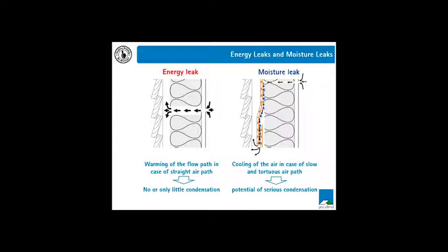If we start to build semi-airtight structures, then we create more tortuous, more convoluted pathways through the construction systems. This gives the moisture-laden air from inside the building in the heating season more time to condense on the cooler surfaces on the outside of the building. And that's when you end up with big condensation problems happening. This is probably where we're sitting now, but we don't really know because we don't air pressure test enough buildings to know how air leaky or how airtight they actually are.